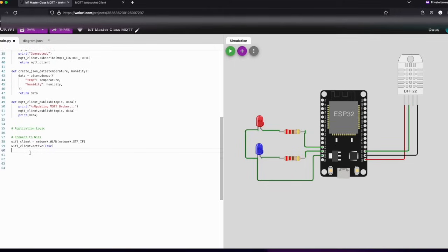Because the Wi-Fi takes a while, usually we want to know when that connection starts. That's the way I like doing it. We'll print out a message that we're about to start connecting, and then while we're waiting for the connection, we'll print out all the messages, and then once the connection is made, we'll see that okay, the connection is complete. So let's do something like that.